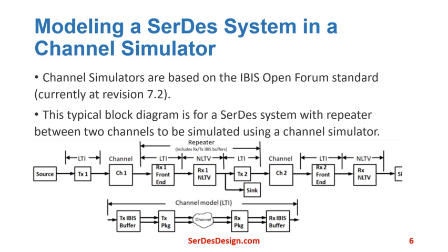Each part is optional and may be represented using S-parameter files. And there's the receiver IBIS-AMI portions. The AMI portion typically contains a receiver continuous time equalizer, a clock and data recovery unit, and a decision feedback equalizer. The IBIS portion has a differential input from the channel.